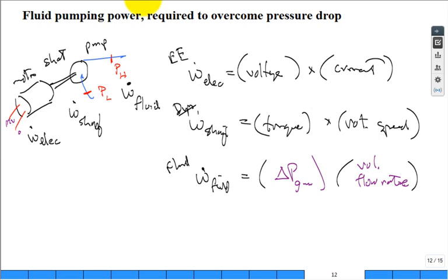Sometimes we're interested in how much of that energy gets dissipated, because you always have an efficiency. So if the shaft power is coming in and you're supplying 900 watts or something like that, and the fluid power is going out 890 watts, where's the 10 watts going? Heating up the fluid. Or it's going into the room, heating up the air in the room. All right.